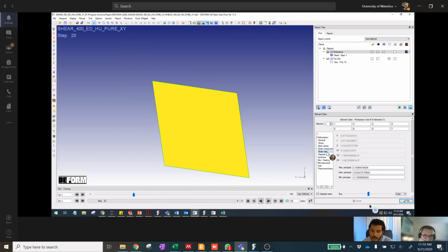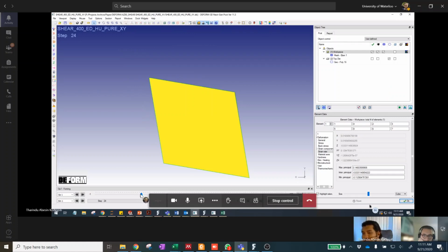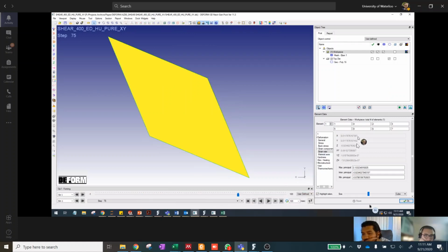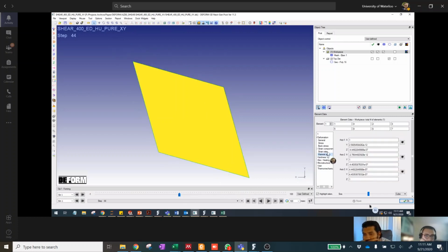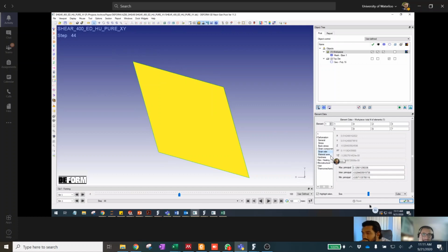So this strain rate plot here, XY is the strain rate that you're imposing, and it's around 0.1, but it's changing throughout the simulation, and all of these other strain rates are non-zero. So that's where that extra deviation in the flow stress behavior comes from at the end when it starts kicking up. As you go towards the end here, these numbers are now large, not large, but they're not e to the -7. So that's part of that problem. But that should get resolved if I remove the other strain rate curves, disable the strain rate hardening or strain rate effects, and make it one strain rate curve. That should fix that problem.